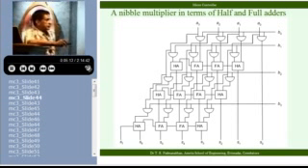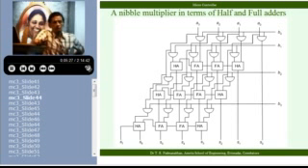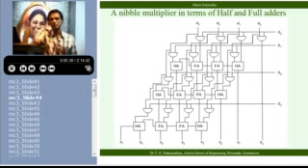In today's technology, typically a circuit like this requires about 50 basic electronic circuits. If I take a NAND gate, that's a universal gate. If I take a 2-input NAND gate, about 50 to 60 NAND gates together, properly connected, can realize a multiplier like this. I have not calculated exactly, but that's the order. 50 to 60 NAND gates will be enough to make a multiplier like this.